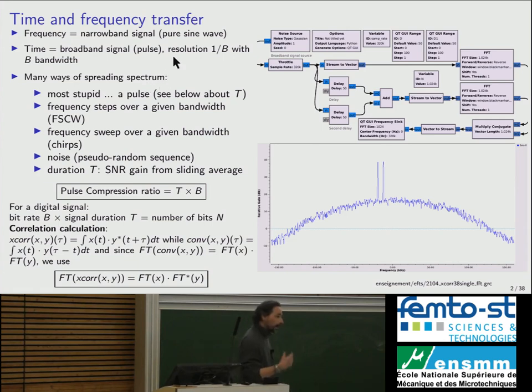On the other hand, time transfer is an intrinsically broadband topic where you wish to have as high accuracy as you can on the timing of a signal that is exchanged between the two speakers. And so that's why you see that these two quantities are actually completely unrelated. You can have a broadband signal that will accurately transfer time, and then you can try to recover some sort of carrier information, you can try to recover frequency information, and one does not preclude the other.